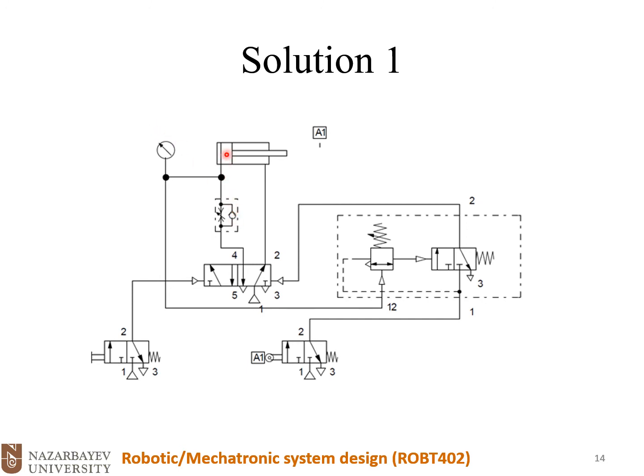Okay, so for the negative control, or the backward motion, we want to reach a specific air pressure. So we want to reach 4 bar here. That's why we have this pressure gauge here, just to examine the circuit and see if it works properly.